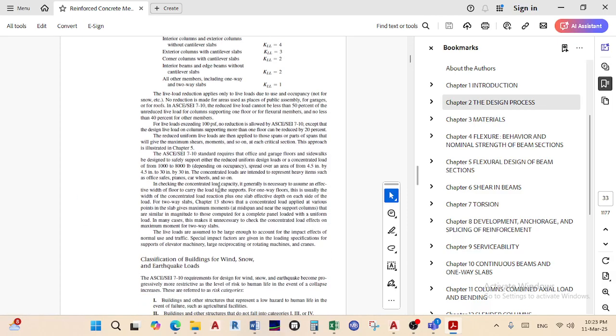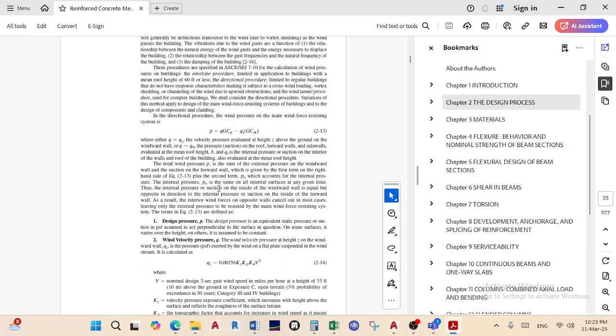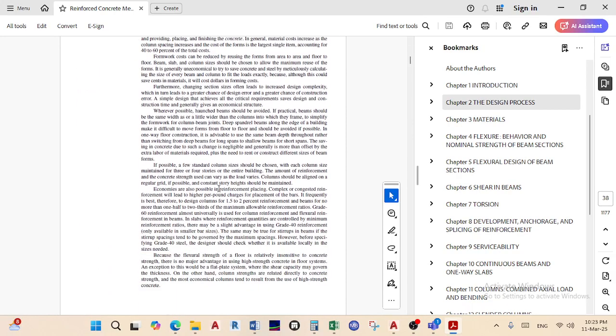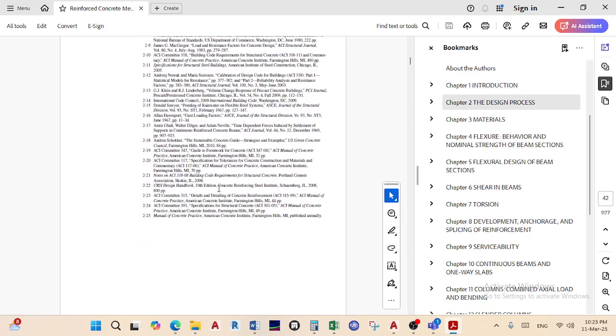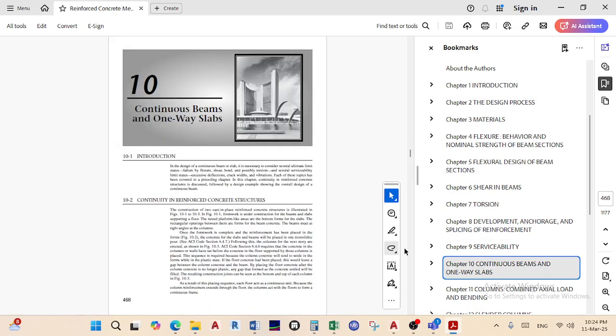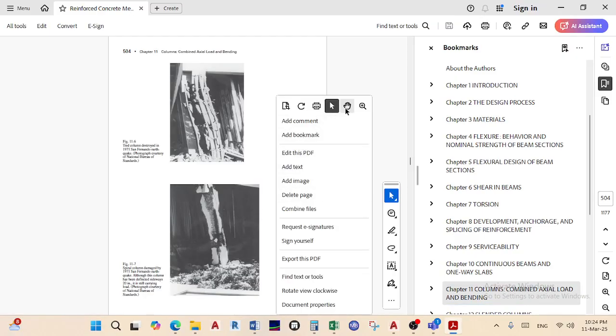So when we go to beams, it's around the same. Okay, even here, these ones have practically refused to pass. Why? Because the steel provided does not give the satisfiable utilization ratio. So we may actually have to change steel, but of course it's not the best way, again, to just change and put.